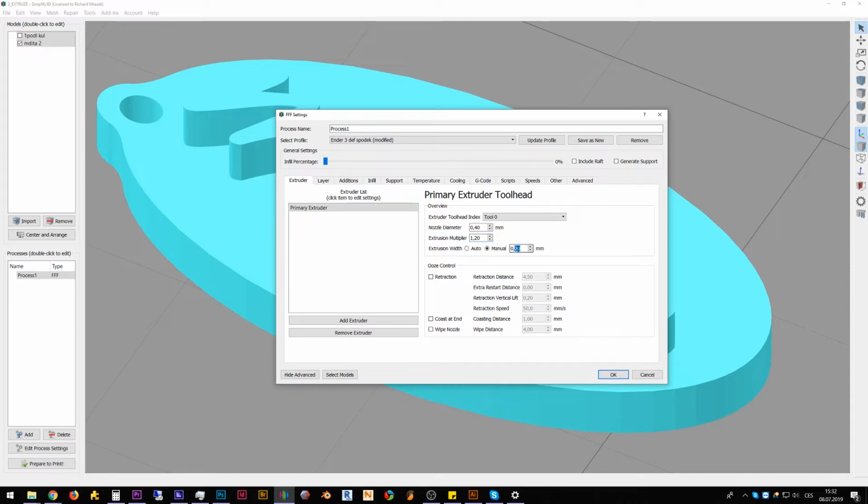The nozzle with this diameter will put a smaller amount of filament, but I can use the extrusion width for drawing small details, and with the dummy extrusion I can add more material to this extrusion. It's not as complicated as it looks, just try it.